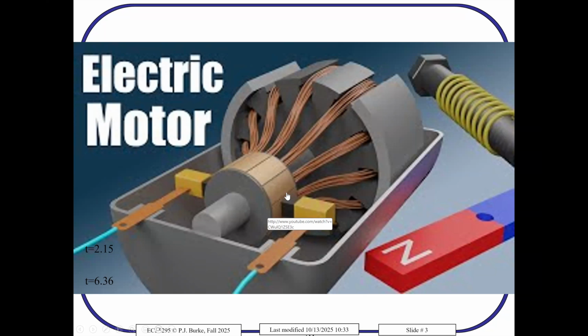It's also simple for the circuit because you notice there is no circuit. There's a battery and there's the motor. Now, by controlling the voltage, you can get more speed or less speed. And we're not going to go into the equations on that, but there's no special circuit to run it. It's called a DC motor because you're providing a DC current and a DC voltage. Whatever voltage you provide determines the RPM of the motor. And the size determines the torque, which determines what kind of a load you can spin mechanically. So it's very simple to use, very simple to understand, but has some disadvantages, the lifetime and the friction.